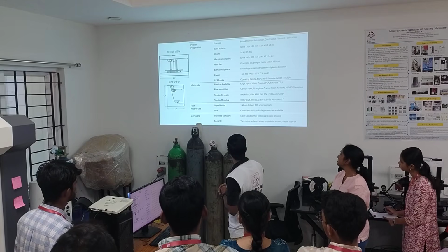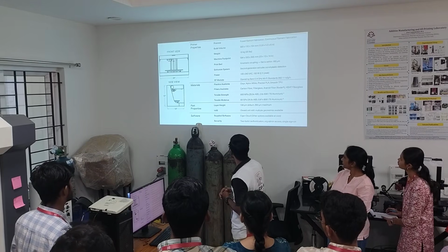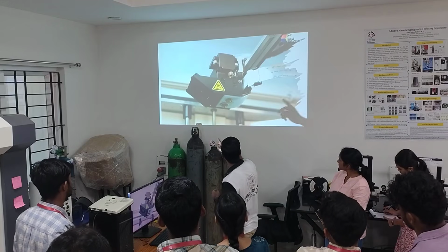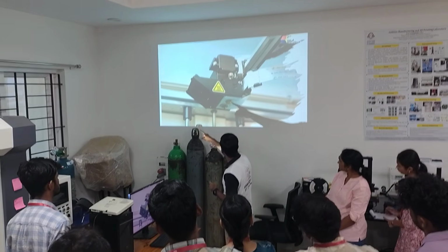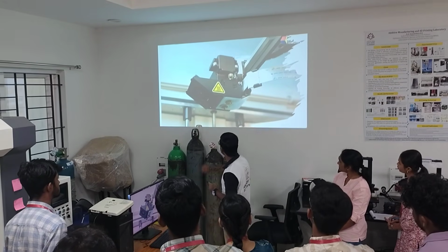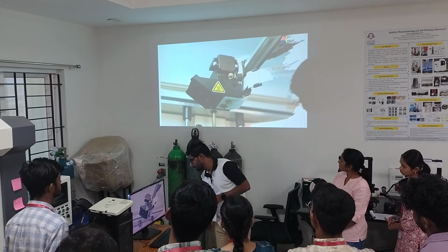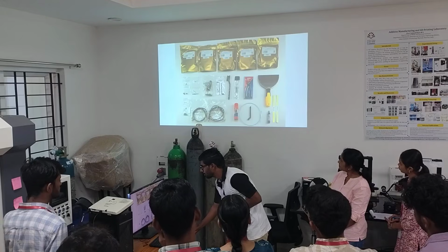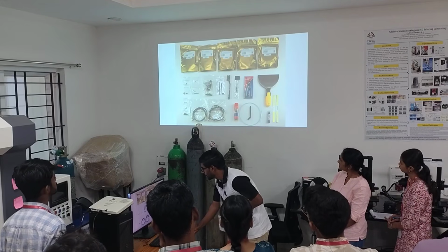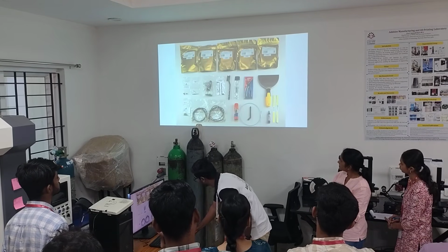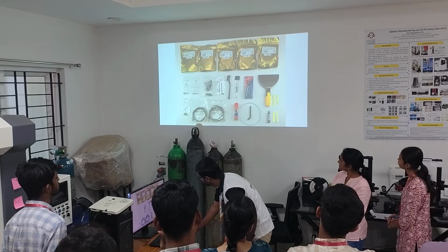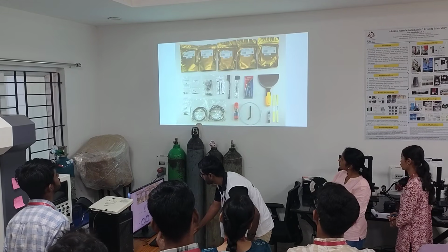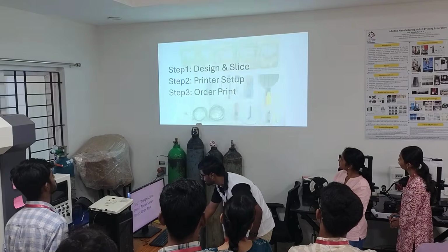They have their own slicing software, that is Eiger Cloud, and we slice on their software. So how will I begin? They have two nozzles. This nozzle is for the fiber, and this nozzle is for the matrix or the plastic areas. So these are a few of the components which they have given to us. This is called a shim. I will be showing you how this can be used for calibrating the nozzle. These are some of the fibers they have given, HSHT fiberglass and other things.